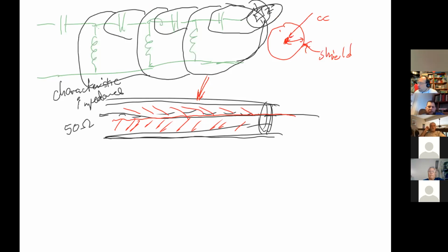Now, most cable that we use has a characteristic impedance of 50 ohms. What that means is that if you have a 50 ohm load, which is what's using your power, and you have a characteristic impedance of 50 ohms in your cable, then looking into the cable from the other end, no matter how long it is, you will see a 50 ohm impedance. That's the definition of characteristic; it's a characteristic of the cable. If your radio is designed so that you have a transistor amplifier with an output impedance of 50 ohms, you have a perfect match. You have an impedance match.